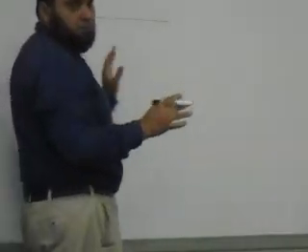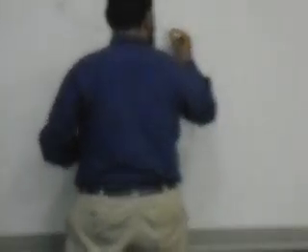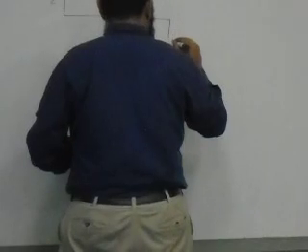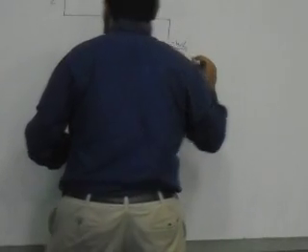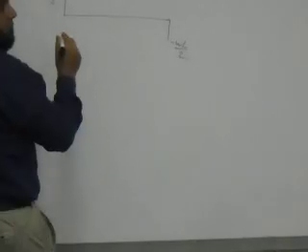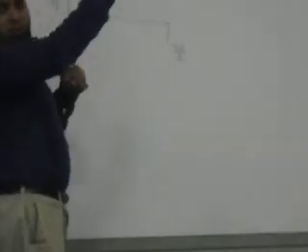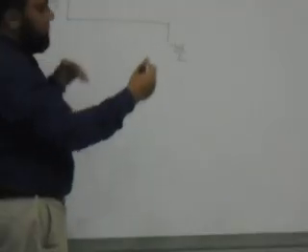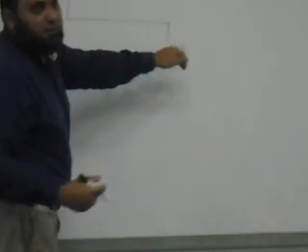Right. So this is simply negative WL over 2. So I'll have here negative WL over 2. And I'll simply connect them with what? Straight line. Because this is a uniform load, we said it's one order higher. Okay, so this is a constant, so this will be a straight line.